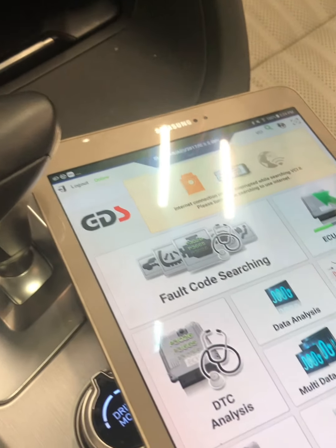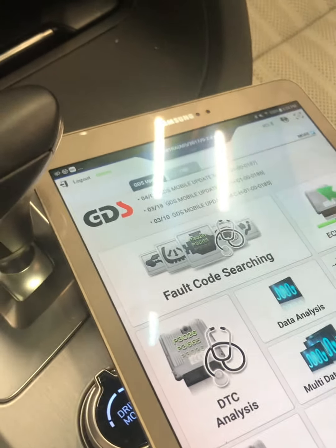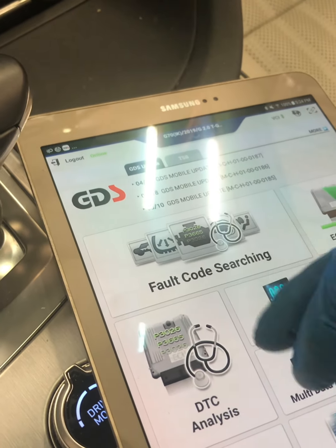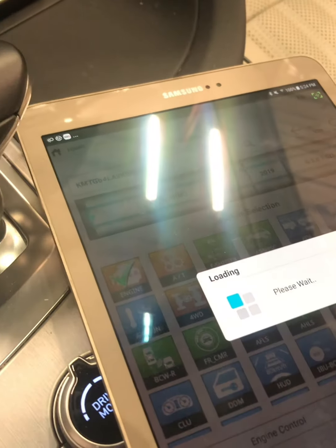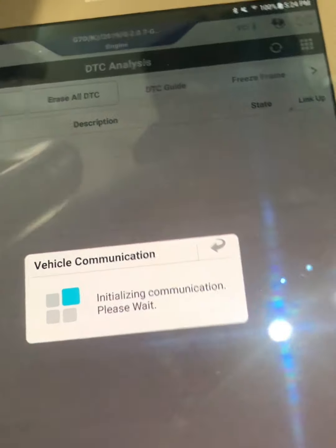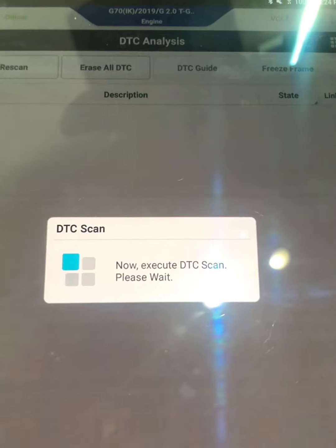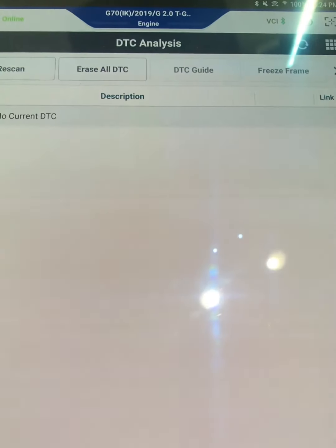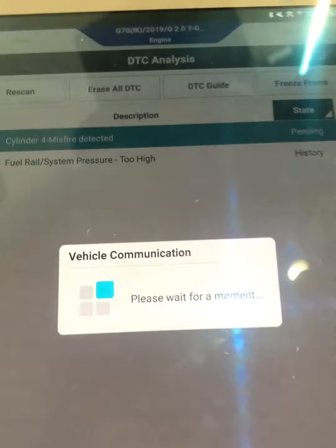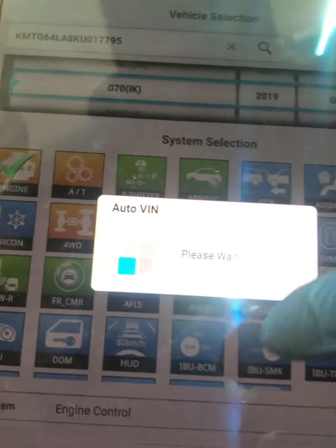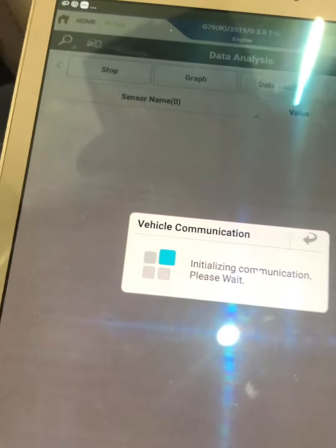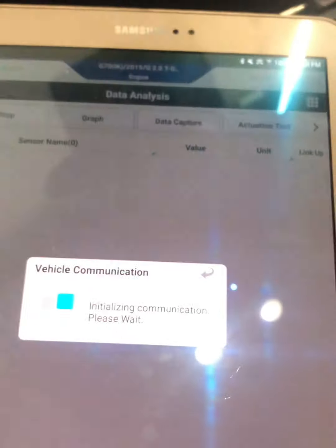I've been waiting a few weeks, about a month, just for that high pressure pump. First, let's check our DTCs. So at least now it's in history. No more misfire codes, that's okay, don't have to worry about that. I'm going to clear it later. Let's just check our desired. Let me start it. Now it's starting, no problem. No more stalling.